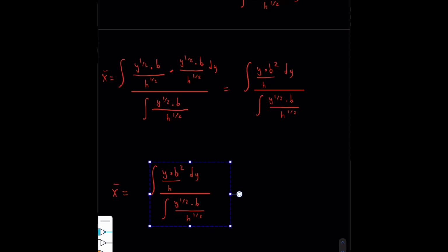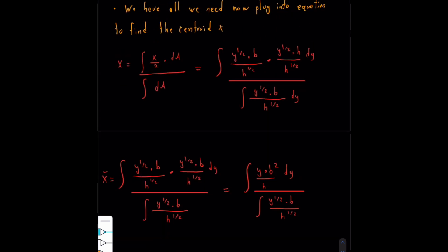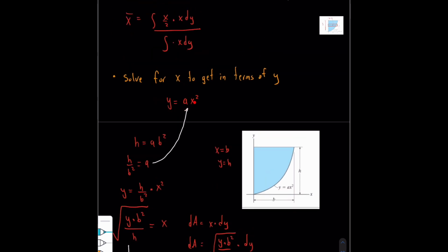Centroid. Okay, so I think I talked about this. Previously I was going to say why we were going to solve for this variable here. As you can see, a could be written in terms of h and b here. Now when we take the integral, we take this with respect to h, because we chose this strip over here.